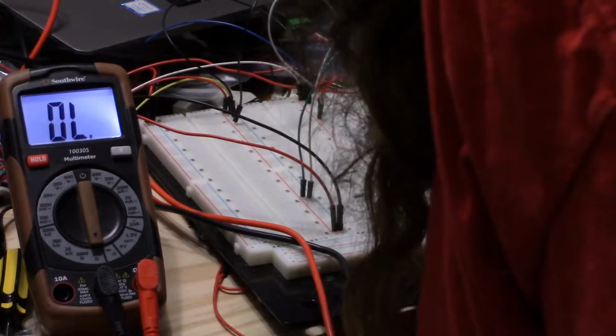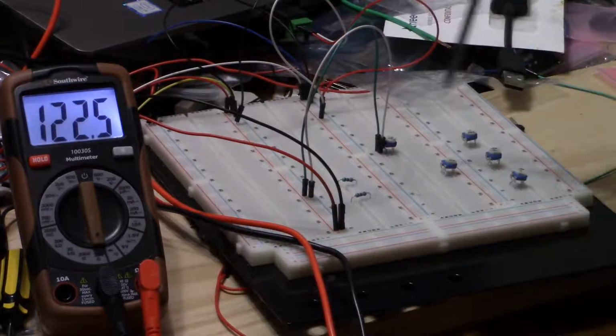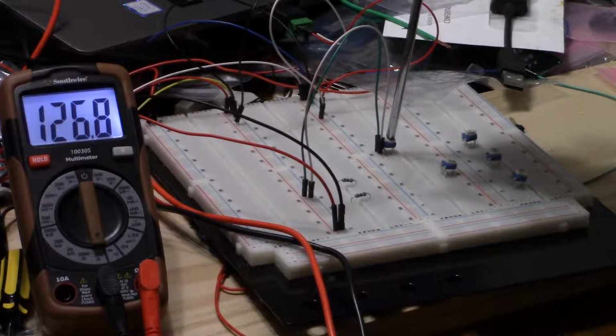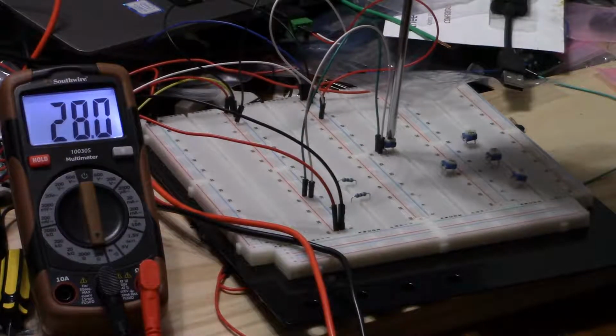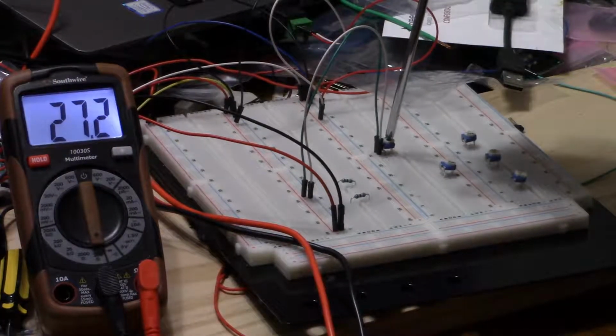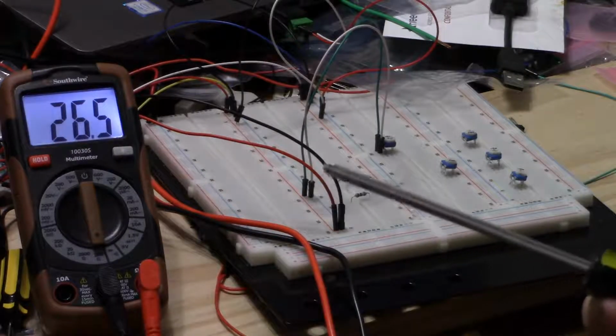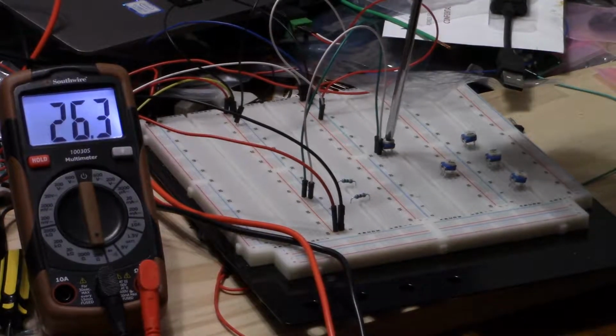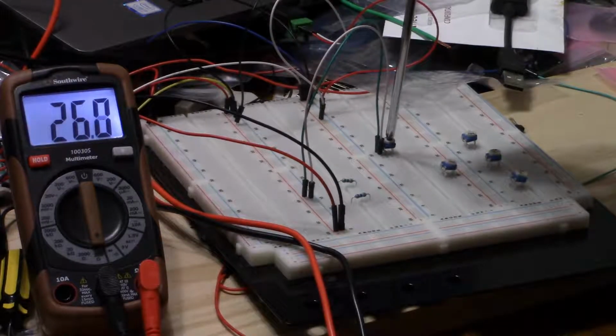This is why we check. So let's try that again. So I'm getting a high value, if I turn it all the way up, of about 127, all the way down of about 27. So even at 0, this is not 0 ohms. That'll be all right, as long as we know what it is. So let's remember we're getting roughly 26 ohms at the lower end.